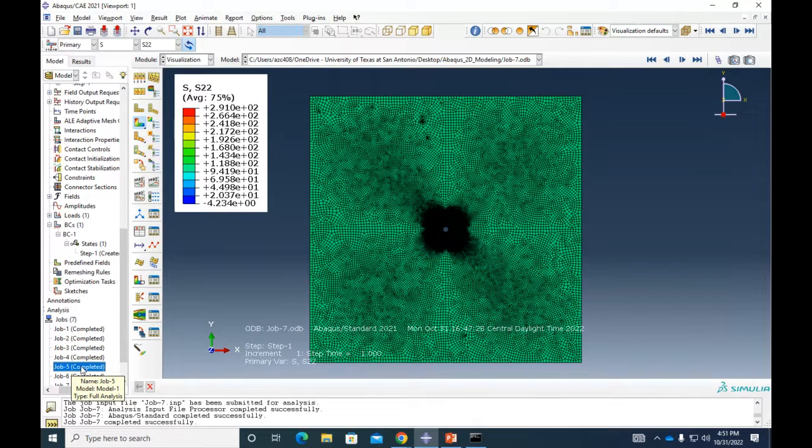All right, cool problem. This is the base for fracture mechanics, believe me. From here, the next step is to add a crack, and that crack has a stress intensity factor, and then Abaqus knows what the stress intensity factor for that crack is, and then you can do crack propagation and things like that. So it's really simple how we move forward from here to fracture mechanics.